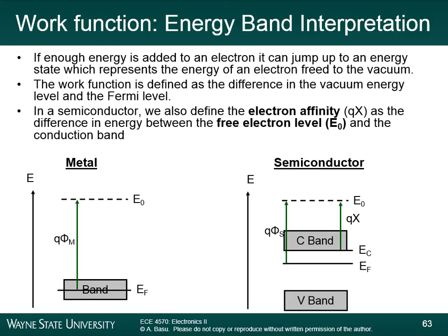In the case of a metal, the Fermi level is usually within the band, somewhere within one of the energy bands. In the case of a semiconductor, the Fermi level is in between two energy bands, and the spacing between those energy bands is small. In the case of an insulator, there's a large spacing between the energy bands, and the Fermi level is somewhere within that spacing. Now, you can go back to Module 3 if you want to look up more on that.